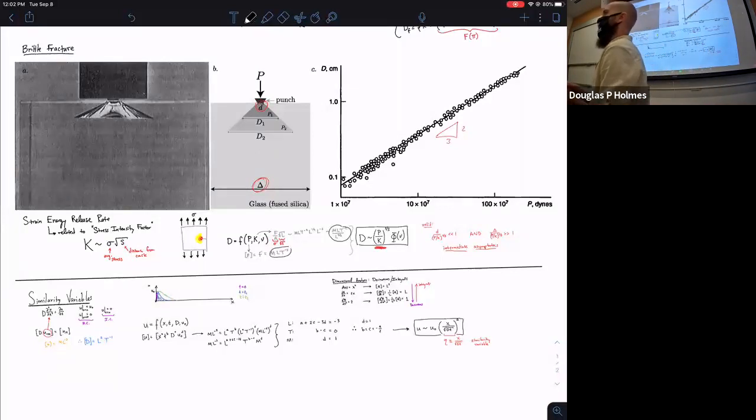Does it also allow you to do, like, experimentally, find different parameters of it? Exactly, and that's the example we gave with the drag on a sphere. You kind of know what you're looking for now. You know what you need to vary, and you know what you need to measure, because you can essentially vary that parameter and see how whatever it is you're looking for, the dimensionless drag or the dimensionless concentration, changes. And so it can be an instructive way to tell you how to conduct the experiments, as opposed to when you have so many parameters, it can be like a shot in the dark.